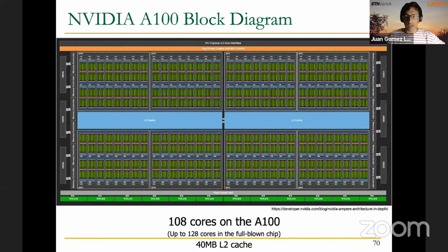And this has definitely encouraged GPU vendors to continue making their devices much more efficient in terms of energy consumption, in terms of performance that can be achieved, providing ways for these cores to access data at higher memory bandwidth, for example, by pairing the GPU chip with HBM memories using silicon interposers that allow these cores to enjoy much higher memory bandwidth. Yeah, we will keep discussing this in later lectures.